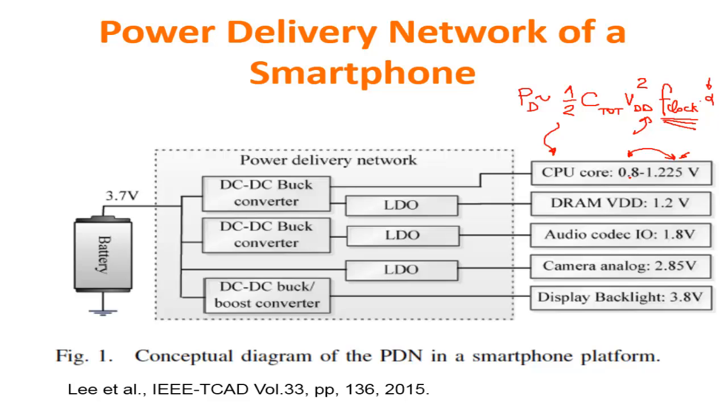There's more or less a linear dependence of the clock frequency on VDD. Therefore a reduction of 1/3, let's say, of the supply voltage actually means a reduction of more than half of the power consumption. So this is something that is typically done.